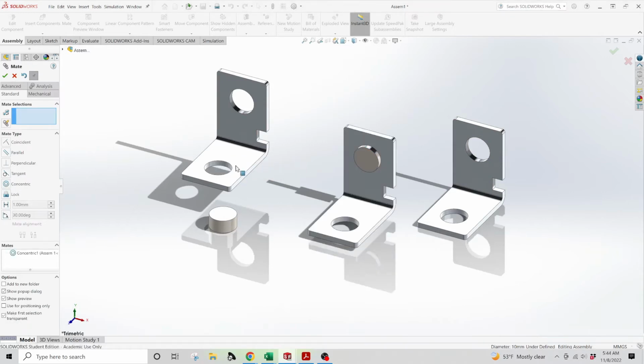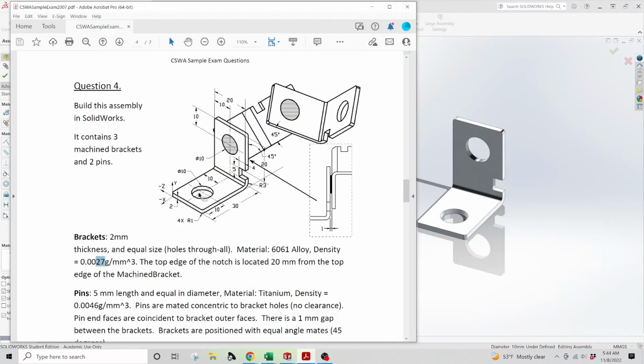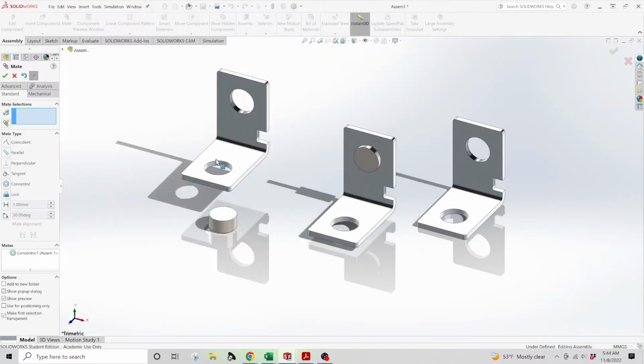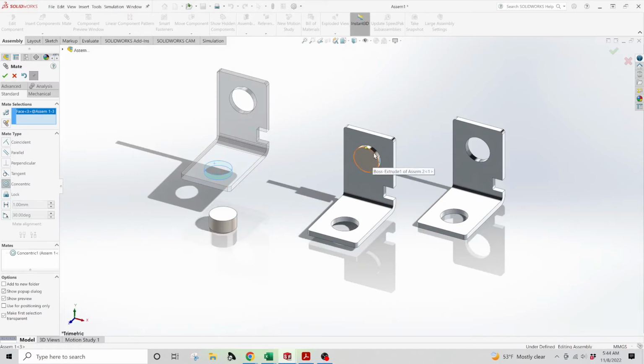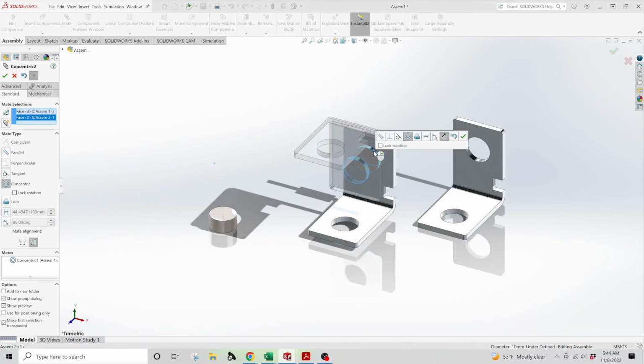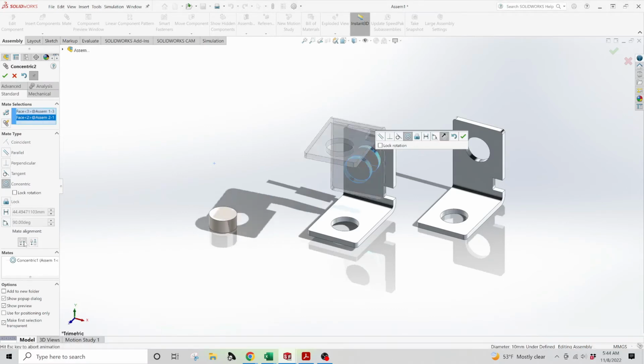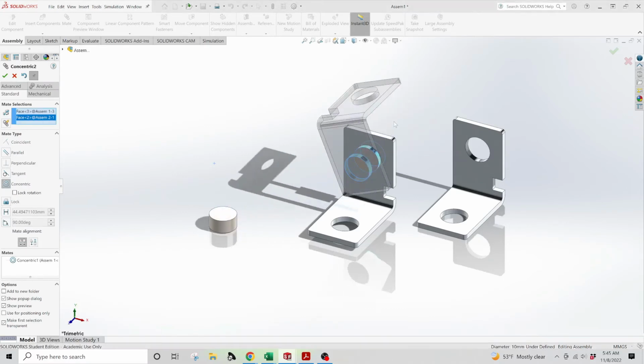We're going to do another one. So we want to pay attention to the orientation here. So this is the one that I started with. It's the reason I drew it in this orientation, didn't do something else wacky. I wanted to start here. Next, I'm going to bring this one into place. So I do that with this single concentric mate. Now I'm going to flip and do an anti-alignment, because it's going to save me a little time.